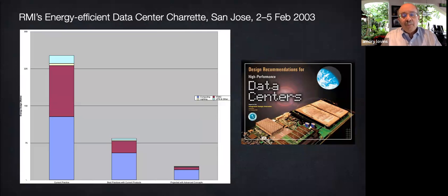We thought that the data center's input energy could be cut from 1.5 to 2.5 plus times the server energy to 1.2, probably 1.13 times. Later, it fell to 1.08, 1.05. This ratio is called PUE. It's now commonly not over 1.1 in the biggest and best data centers.